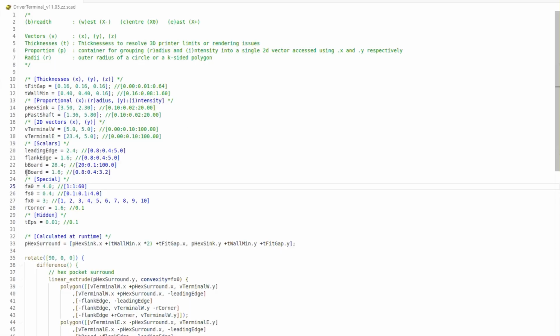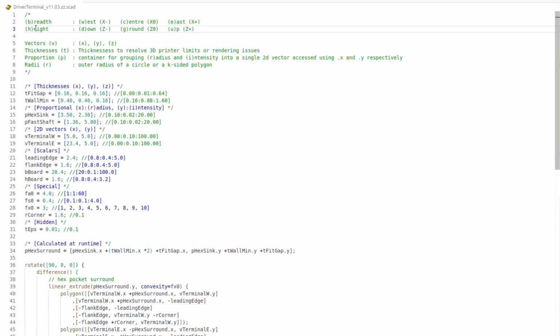And because I'm introducing a new H prefix, I want to make sure that I include comments to describe it effectively. Oh, the other thing I forgot to mention. Practically speaking, although this fastener will be seated like this, there's usually going to be a washer situated between the head of that fastener and the actual PCB board. That washer is useful because you're twisting that fastener in and you don't want to damage the PCB board. The other thing that's happening is that washer is going to hold the spade connectors in much better.